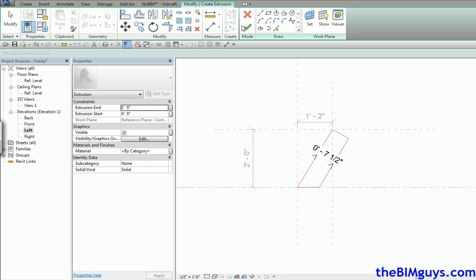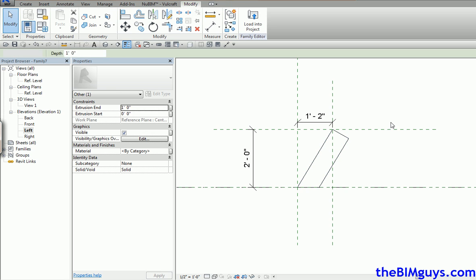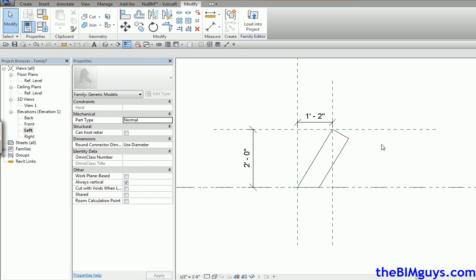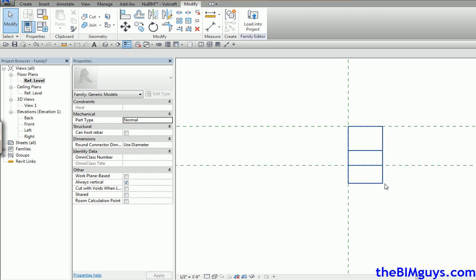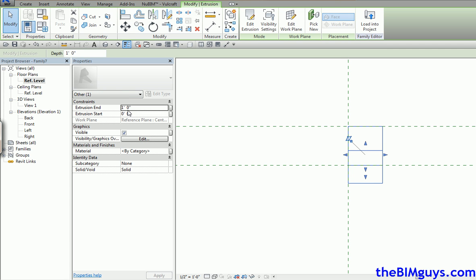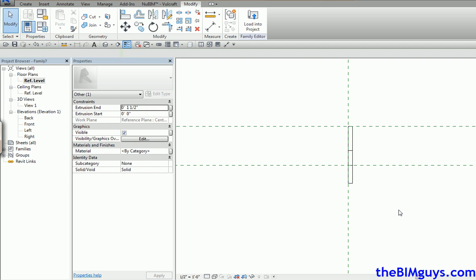What I've done is I've just created a solid, or there's my solid. Let's go back to the top view. Now when we look straight down on it, you'll see it's pretty chunky. It's actually a foot thick. I could come over here and adjust this width here. I could have done it before I built it, or I can adjust it after. I'm going to say the depth of this thing is 1.5 inches. And there it is. So what we've done is we've created the rafter.